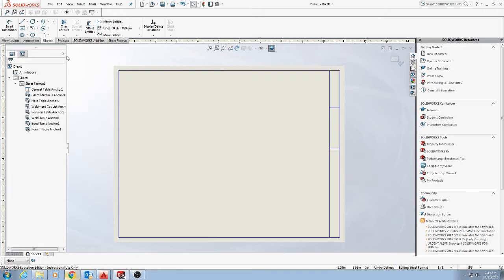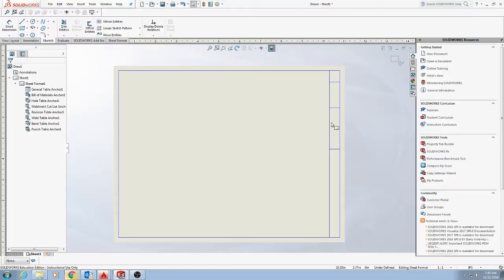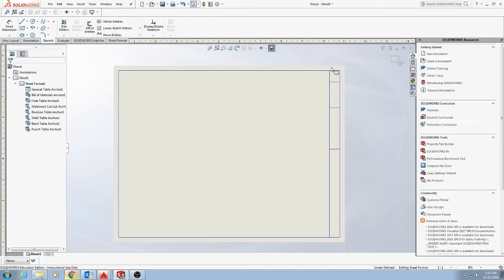Oh boy. Try that again. Offset. Click the line. I forgot what it was. 1 1/4, 1.25. Enter. Check mark. Okay, and erase that. There should be about a 1/2 inch left. Not exactly, because I'm not following the exact dimensions of these whenever I created the border around the outside. So we'll just call that a slop dimension, and whatever's left over there will be fine.